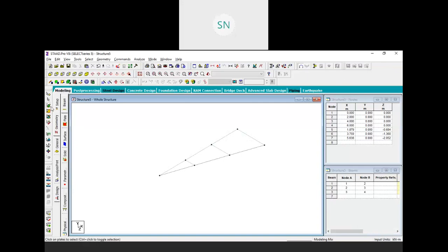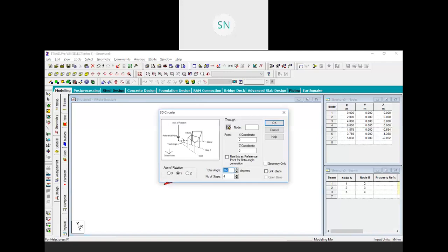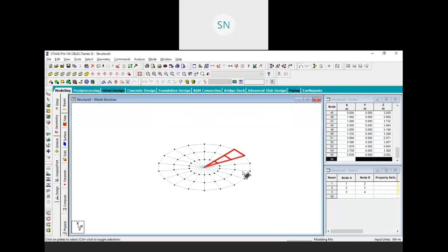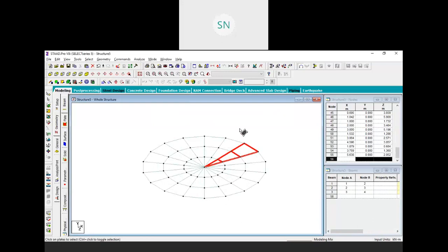So take a plate cursor now, because these are plates and you need a plate cursor to select them. Take circular pattern in 340 degree, because we have already 20 degree, and 17 copies. Click OK. So now we have an entire plate like this.